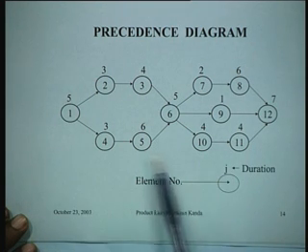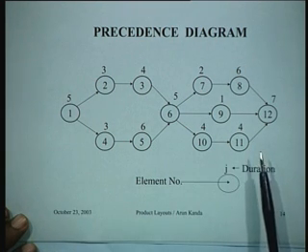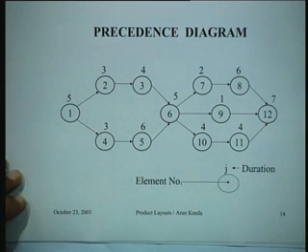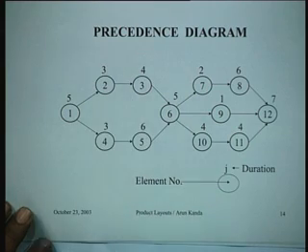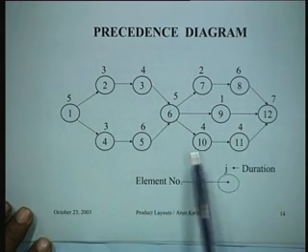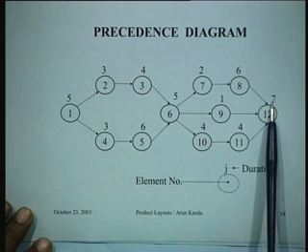So let's see how we can design an assembly line manually for this operation, and then we'll compare it by using the ranked positional weight technique. Now clearly in this particular case we are going to group these operations. So one thing is clear: what is the maximum time that is required for any operation? That is 7.